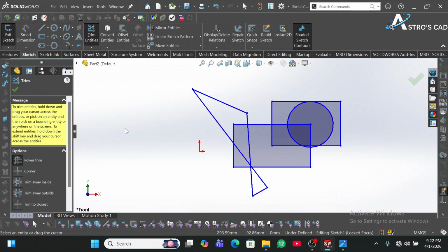are not needed. And the way it cuts lines is any line you cut across is going to cut it. Let's say I cut across this line now. It's going to cut it from this end point to the next point, to the next intersect actually. It cuts all the way to the next intersect. Make sure you're on power trim. Leave these ones, later we may discuss them.